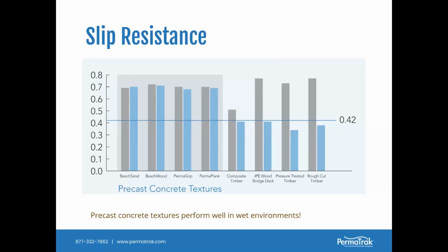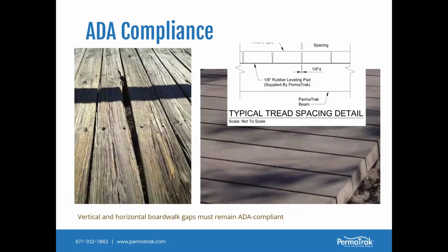So what you'll notice is everything does well when it's dry, but when you add water, the composites and the woods just don't perform as well, which I think we all would have seen, those slippery when wet signs around wooden and composite boardwalks. Just something to be mindful of. So it's a public safety issue. And then you can start looking at ADA compliance. Again, another public safety issue. So rigid systems like concrete tend to stay in compliance, but wood and composite over time will warp and twist and then come out of compliance.